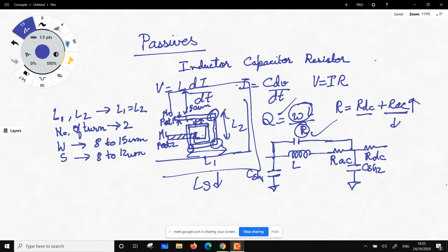Another thing is you can run just a piece of metal between the two ports, but then the problem is the connectivity, right? So let's say this is ground between two ports. If your circuit requires it, you have to rotate your inductor in such a way that you can establish the ground continuity between the two ports. So you might have to cascade other components. Other components will come this side or that side. So you can rotate this if you want, right?